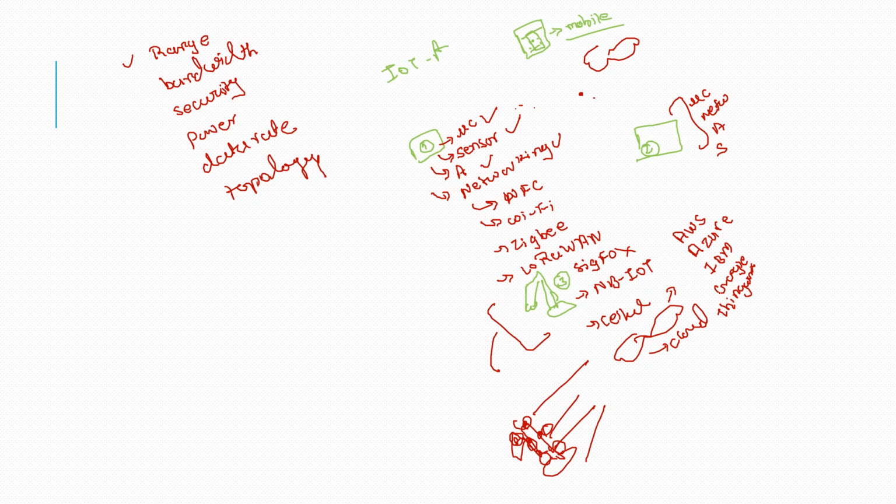For sending email through the internet, we generally use SMTP, POP3, or IMAP. For IoT domains, we generally use the MQTT protocol, and with it we can easily implement this part. All of these cloud platforms support the MQTT protocol, so we can program it and interface it with our microcontroller to push the data to the cloud. Once the data is on the cloud, we can work on it and build different kinds of applications. We'll also do some practicals and a demo on the MQTT protocol.